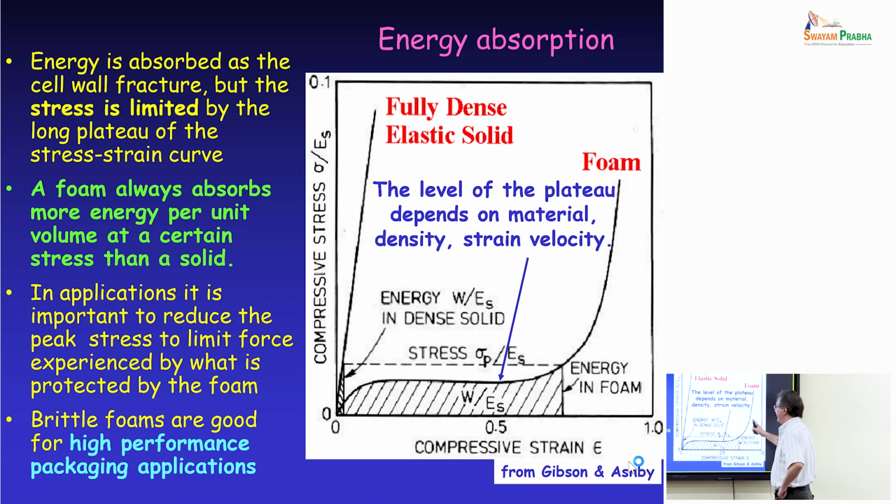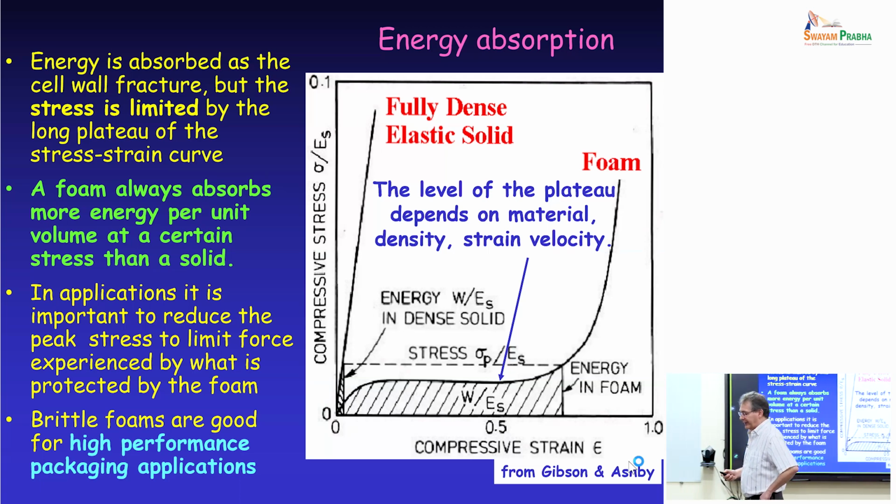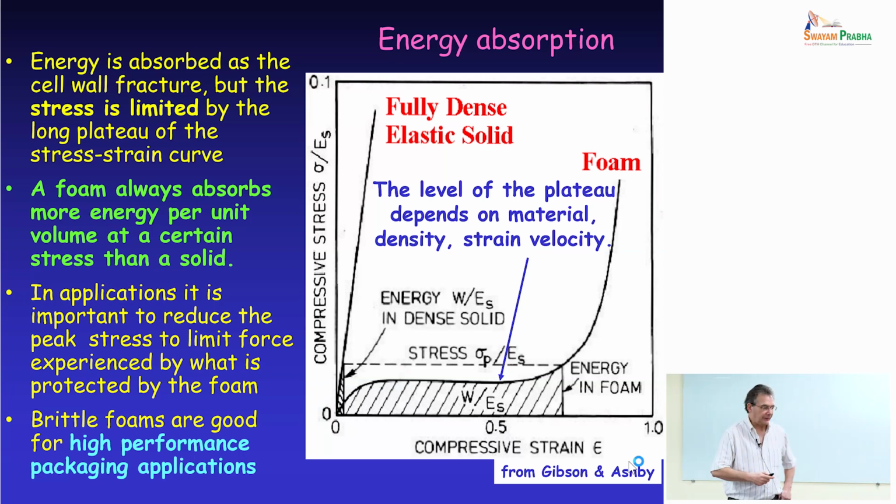So the fact that a foam fractures in this way means that a foam can absorb more energy per unit volume at a certain stress than a solid. This is for a polymeric foam, but the same thing you can say for ceramic foams. So brittle foams are actually good for absorbing stresses, despite the fact that the maximum load they can sustain is limited by the presence of porosity.